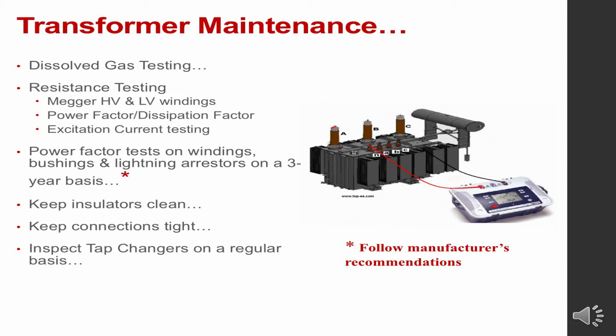Keeping the insulators clean cannot be overstated, especially if you're in a dusty environment. One of my customers, for example, often will polish metal tanks, and there's a nice layer of metal flakes all over everything in the plant, it seems. And of course, aggressive maintenance would need to be there so we don't get conductive paths tracking, in other words, that would cause faults. Keeping the connections tight is also important.